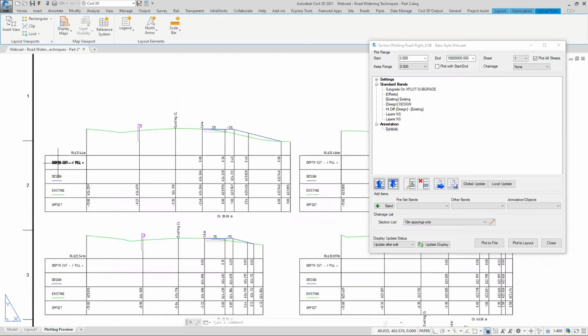First of all, we've got the height difference band. That height difference band has been added using height difference. So very, very straightforward, just with the cut and fill. That's been added up into this particular section. The key thing is sort of the key areas of this. First of all, the design is being told to be constrained 1 meter past the batter.